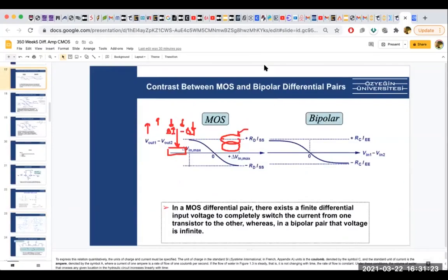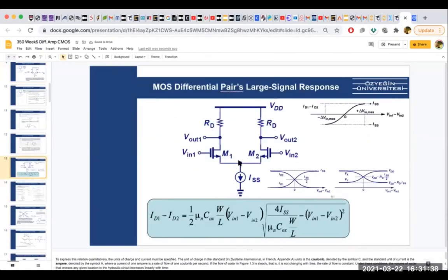If you go back to the virtual ground concept, this is ground because the actual delta V increase is not changing this voltage. The current increase is circulating here between these two nodes. So in the example I gave you, this is 5 volts, this is 5 volts, this is fixed. If this becomes 6 volts, and this becomes 4 volts, well, this is still 5 volts, right? It doesn't change, but you see the current flow from here to here, right? 6 to 4, from high voltage to low voltage. Yeah, it's exactly the same logic. This voltage may be going high, maybe this voltage going low, or vice versa, and it's creating a flow here. There is no extra current flow here.